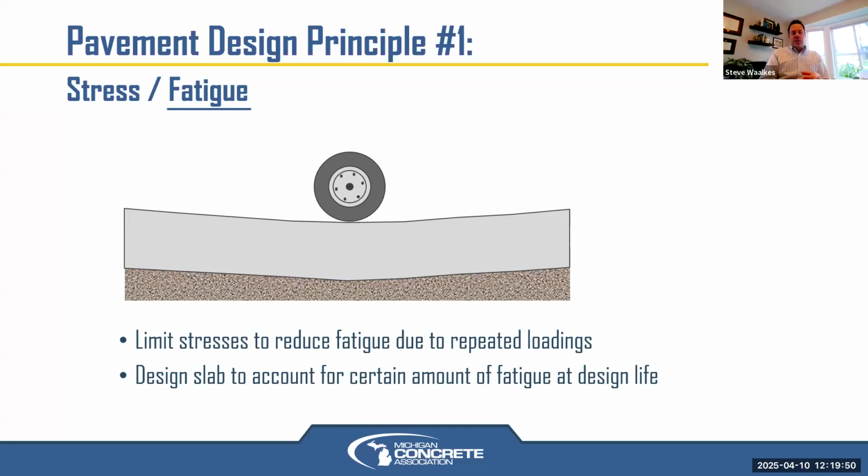But the concerns with too much cement, yes, more cement means more shrinkage, and generally more cement, especially once you get above probably 6.5, 7 sack, means reduced durability with most mixes that we see. And with more shrinkage, you have more opportunity for extra, uncontrolled cracking that you didn't anticipate. It also increases the cost. So, not recommended. It's good to have a reasonable upper limit on that cement content.